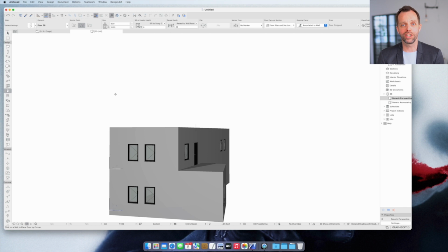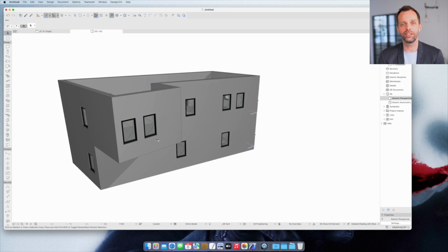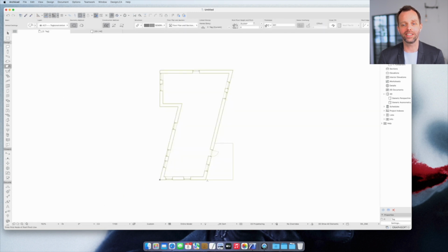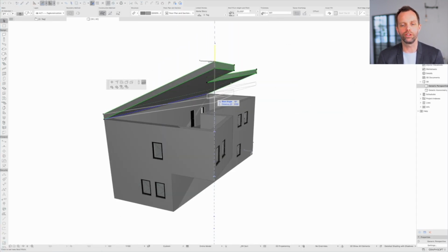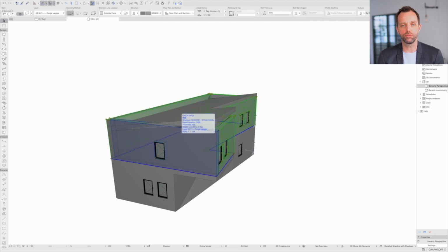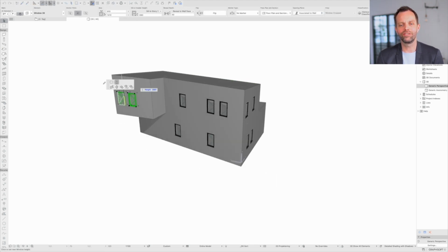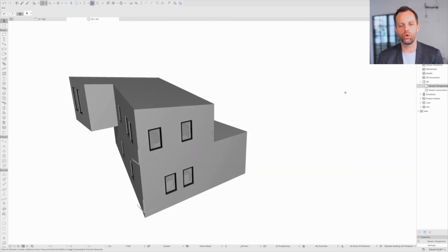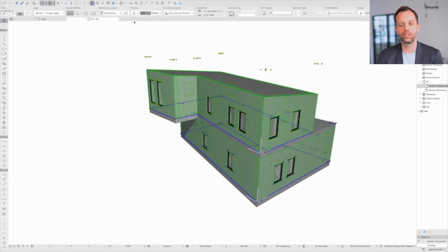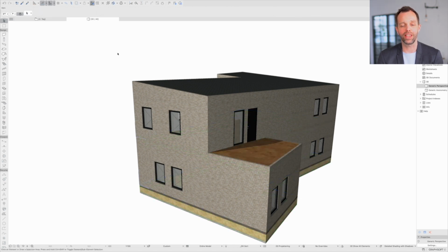But you'll be able to do a template like this. Some countries are also already working to provide Archicad templates with LCA data. So it's still a real world example. So I'm just modeling a building from scratch, so there's no cheating. And it's important to figure out what kind of detail level makes sense for doing the LCA calculation. Right now, I have massive walls made of nothing, so I changed them with a composite, so now I have real materials on walls, slabs, and roofs.